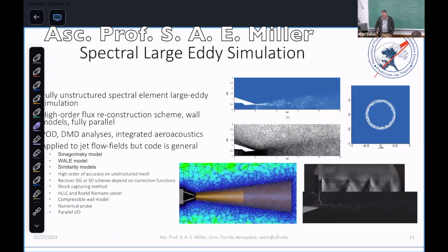Okay, now there's a new technique. If you look at the finite element method, maybe of Galerkin formulations, those do not work for CFD. They're often numerically unstable. They'll use things like discontinuous Galerkin methods with upwinding, meaning we're taking differences in the opposite direction of the flow because of stability. And I had a Ph.D. student who graduated, back from China, but he helped develop this with Stanford and NASA Glenn Research Center, called spectral elements.